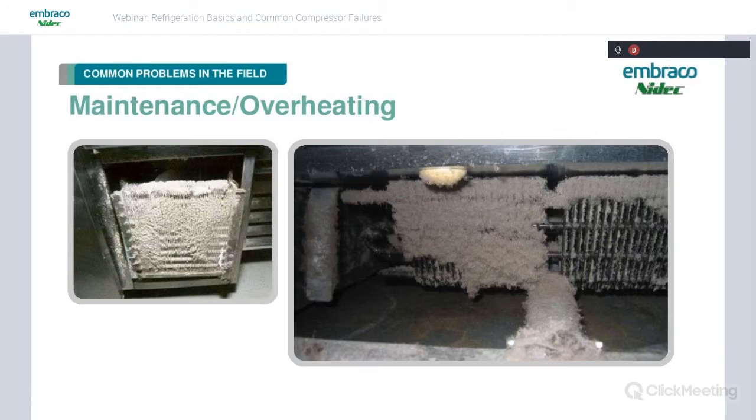It's going to get the oil so hot, and the compressor is going to be so hot, it's going to cook the oil inside the bearings, and you're going to get all kinds of debris, and the oil is going to get cooked on the bearings and everything. It's going to cause all kinds of problems. Your valves aren't going to seal good anymore, and then it's all downhill from there. And if it gets too bad and it runs like this for too long, it may not trip the overload. And then the technician finally goes in there and cleans all this up, and you've degraded your oil so badly that it broke down and clogged up the cap tube. So obviously very important to do a good job of maintaining this equipment.